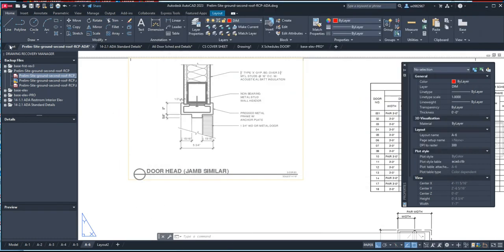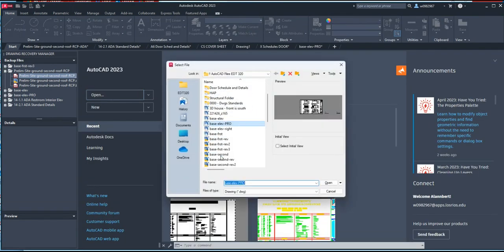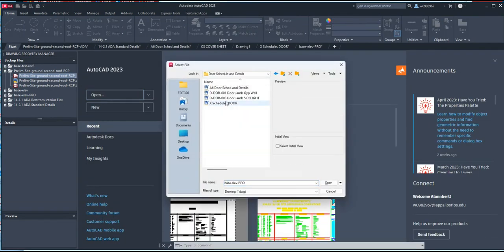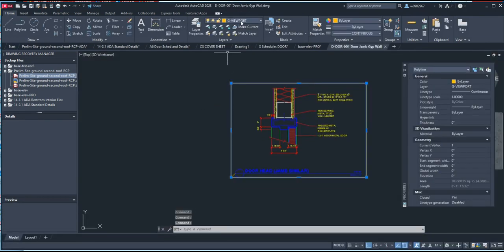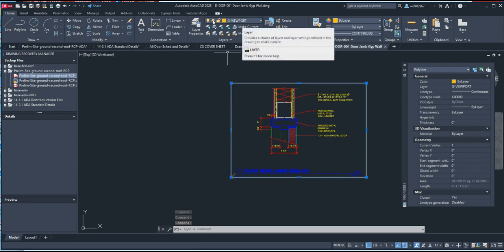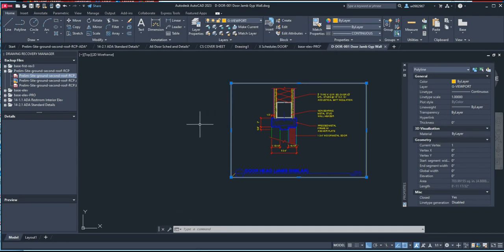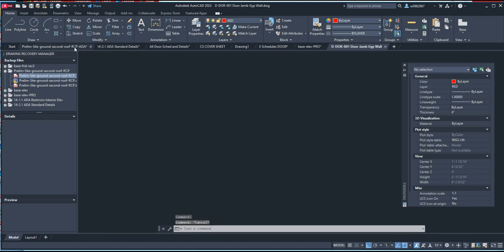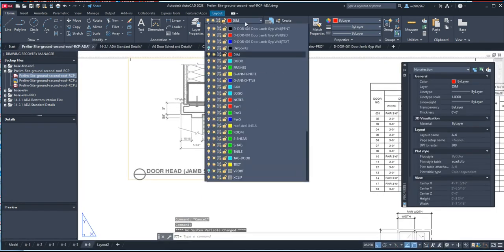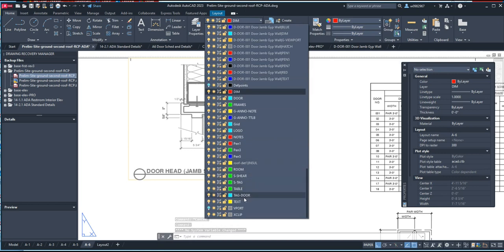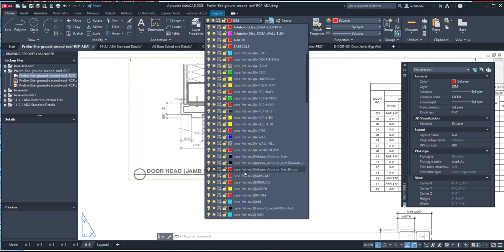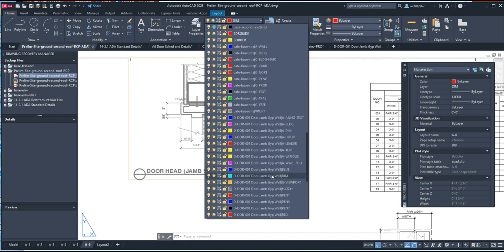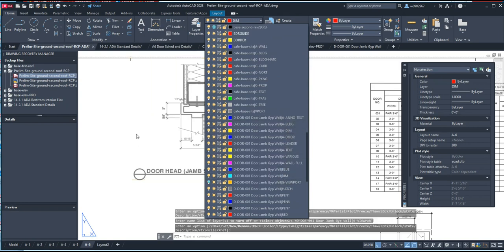The layer of this one, let's open that file. Oh, not that one. 001. Just to show you. You may need to edit this one. This one is a viewport, and that's supposed to be turned off. Okay, after inserting. So when you go back here, make sure that your layer viewport before you print would be turned off or frozen. Door 001 layer viewport here. Turn that off and you don't see it.